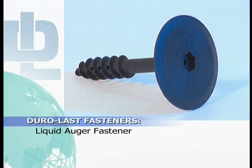The Duro-Last liquid auger fastener is a composite nylon and fiberglass screw that has a 3-inch diameter stress plate head with an internal hex head drive. The fastener can be installed with a 9/16 inch hex head screw gun adapter bit that is supplied with each order. The liquid auger fastener is designed for attaching insulation and roofing membrane to lightweight concrete, cementitious wood fiber, or gypsum decks.